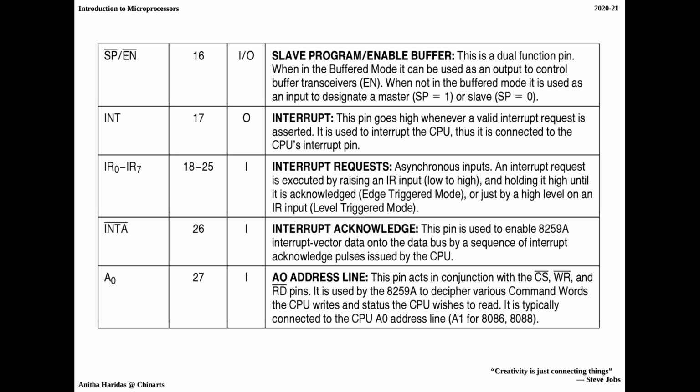If it is buffered mode, it will specify whether it is used for transmitting the data or receiving the data. Whereas in the non-buffered mode, it will specify whether the controller is a slave controller or a master controller. That is what you have to understand here.